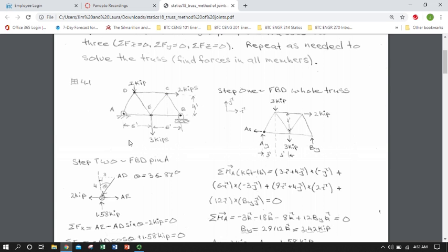So as you can see, this is setting up to be a big system of linear equations, and is in fact one of the reasons why the method of joints is typically solved the same way DC electric circuits are solved with Ohm's law: linear equations, with a method of matrices.